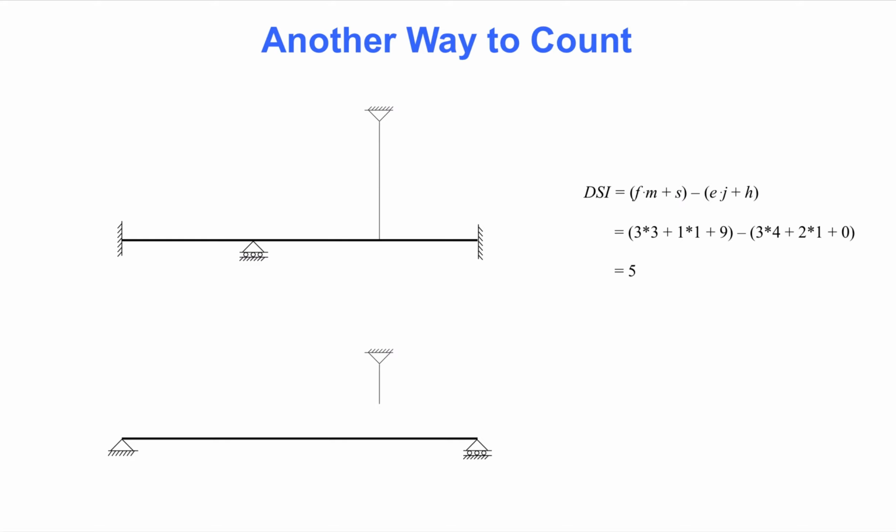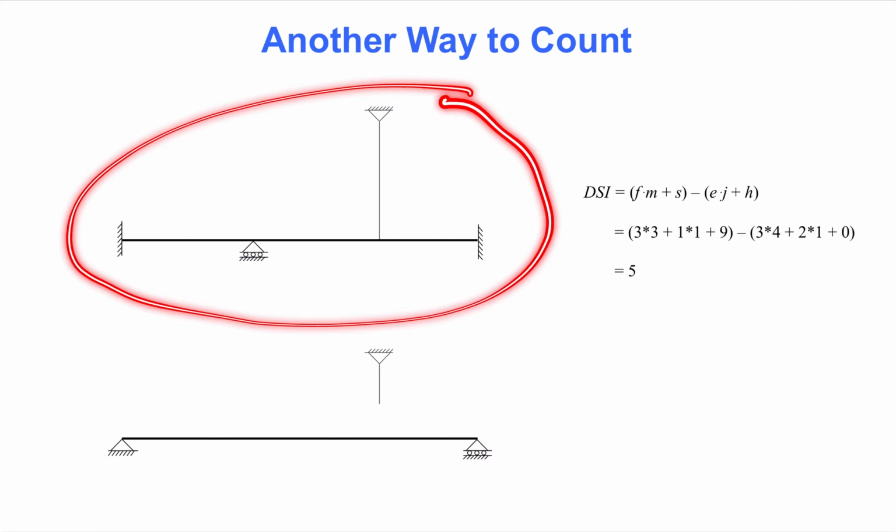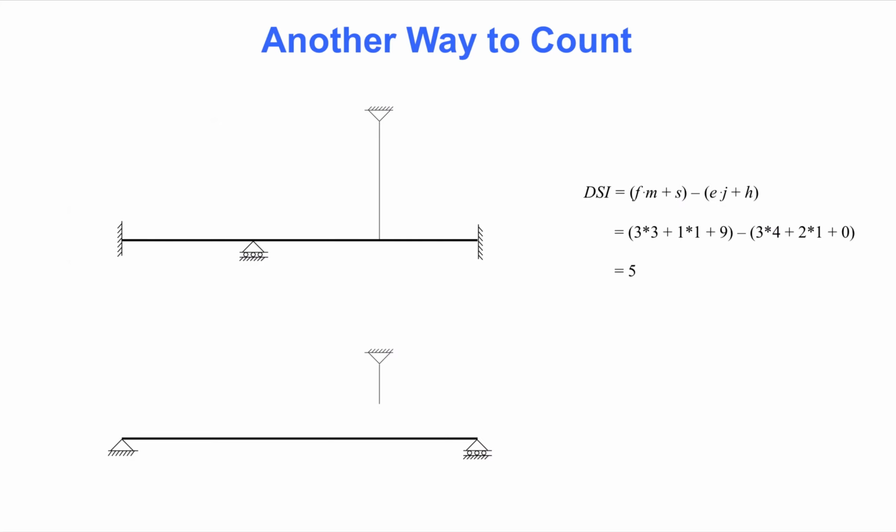Toolbox. This slide shows a structure with one truss member carrying a continuous beam. One way to count the degree of static indeterminacy is to cut supports and members until the structure becomes unstable. The maximum number of cuts you make while the structure is still stable is the degree of static indeterminacy. This is an error-prone approach that takes some experience, but let us consider this structure. First, let us cut the capacity of the left-hand side support to carry moment. As a result, that is now a pinned support. Next, let us cut the vertical truss member.